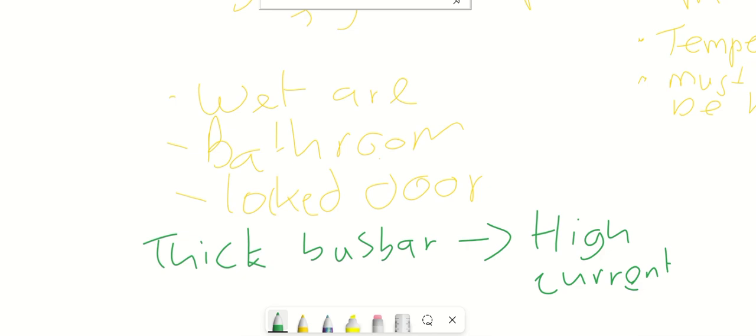Okay, miniature circuit breakers. Miniature circuit breakers protect the circuit from overheating, overcurrent, short circuits, and it automatically switches off the circuit. So normally when something trips, the electricity just goes out, but on your distribution box and your meter box there's still electricity.